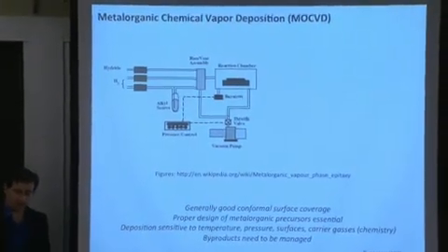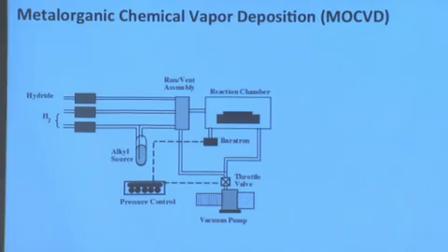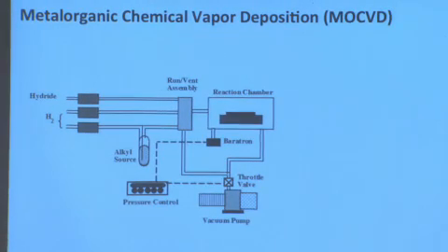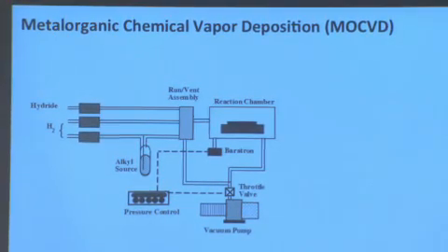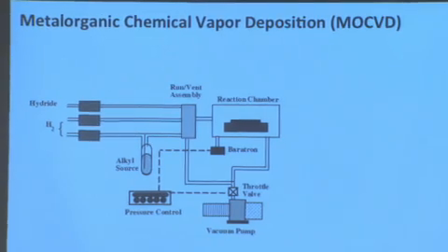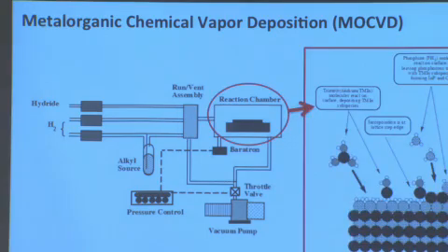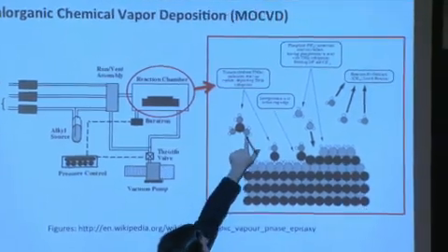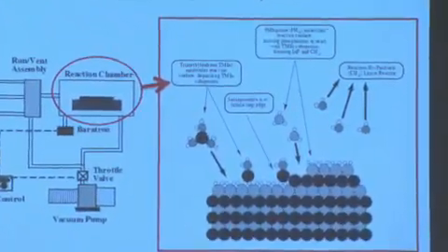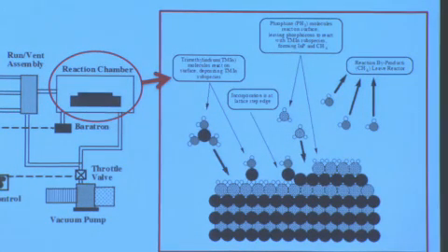Let's talk about the next technique that is commonly used in thin film, inorganic thin film deposition. This is called metal-organic chemical vapor deposition. So again, we notice the CVD appearing at the end. We know it's a chemical vapor deposition process. MO, in this case, stands for metal organic. The reason is that we typically have a metal, like this representing the indium right here, and then little organic compounds on the outside. Those are methyl groups, the little gray and the two white dots. Those represent 3 methyl groups around the indium, so trimethylindium.